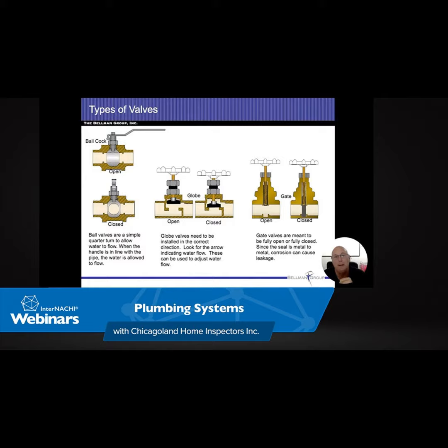The cure for lead water services: if you put in a new water line coming in there, you might be looking at 15, 20,000, and it might even be more depending on the run to get to the street and the tap in. They're going to have to bore underneath the house. Typically, the new line's going to have to be 10 feet away from the waste line, so it's not going to be in the same trench anymore. It's kind of a big deal.